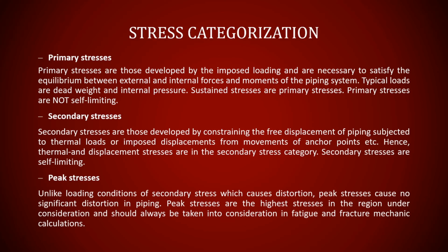Peak stresses. Unlike the loading conditions of secondary stresses which cause distortion, peak stresses cause no significant distortion in the piping. Peak stresses are the highest stresses in the region under consideration and should always be taken into consideration in fatigue and fracture mechanics calculations.